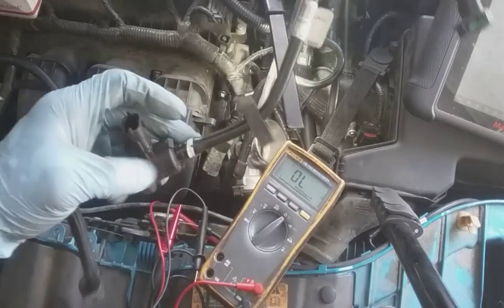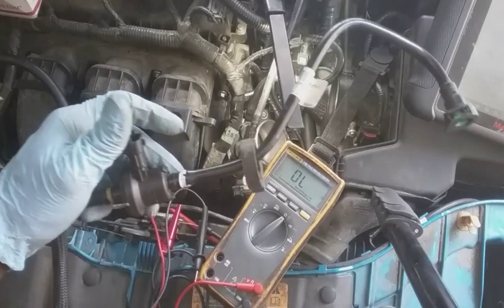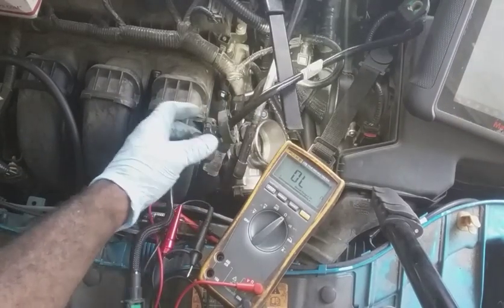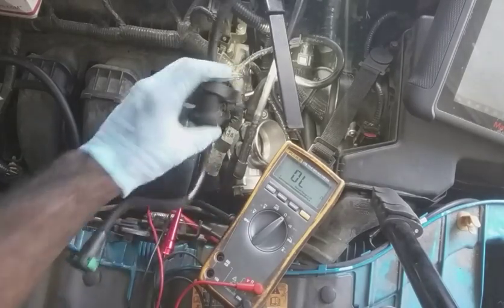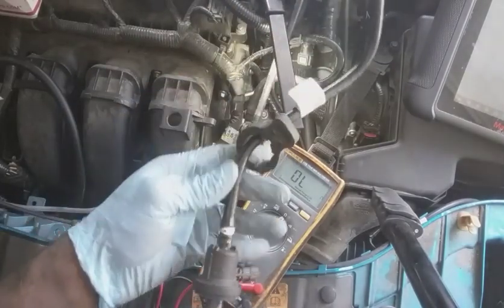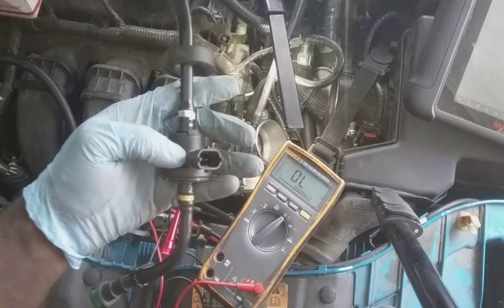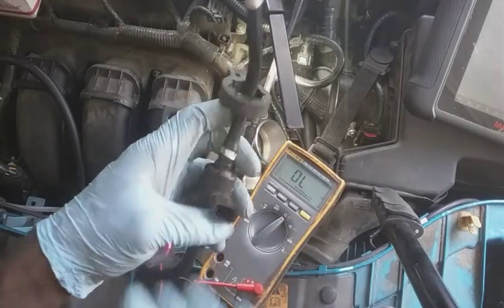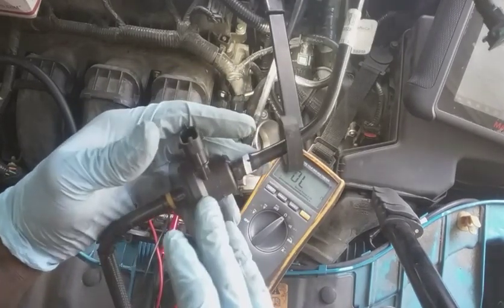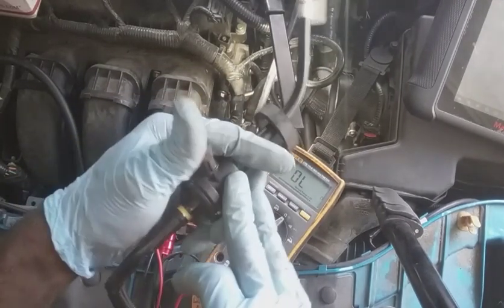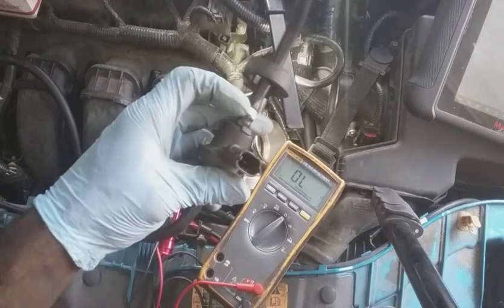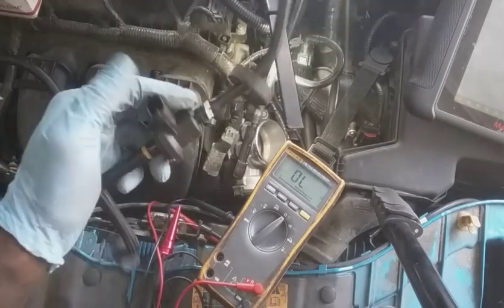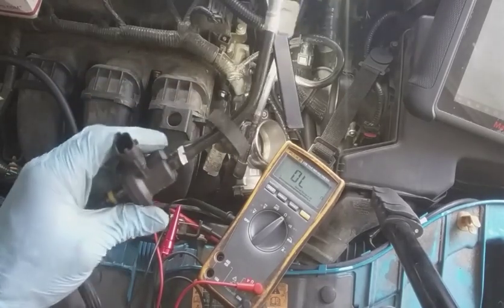Now, despite this car having just intermittent issues, luckily I was able to catch this problem when it happened with the smoke tester. So I'm still going to replace this because it's getting stuck open, and in its natural state it's supposed to be closed. When I get the new one, I'll do another ohm test and see what that one comes up with.